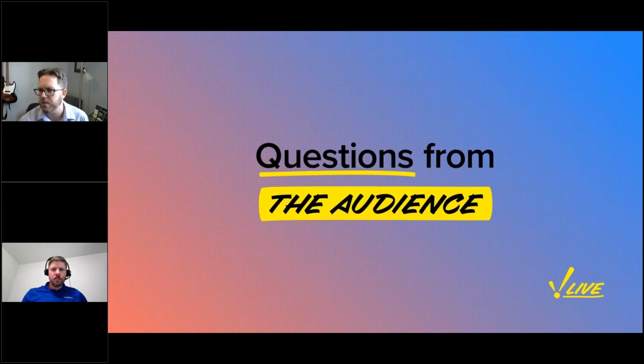Next question was from Andrew, asking if we needed our tags structured in an ISA 95 equipment model for OEE to work. I really liked this question. The answer is technically no, but you almost definitely want to do it. Again, it's availability, quality, performance, good parts, bad parts, downtime codes, the data you need for an individual work cell or line, which is fairly simple and seems pretty achievable.